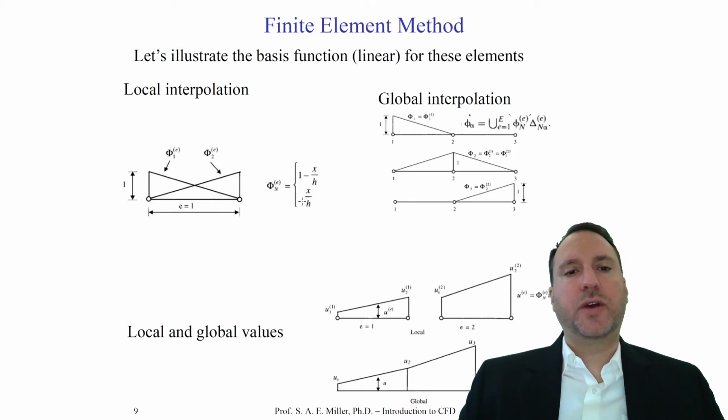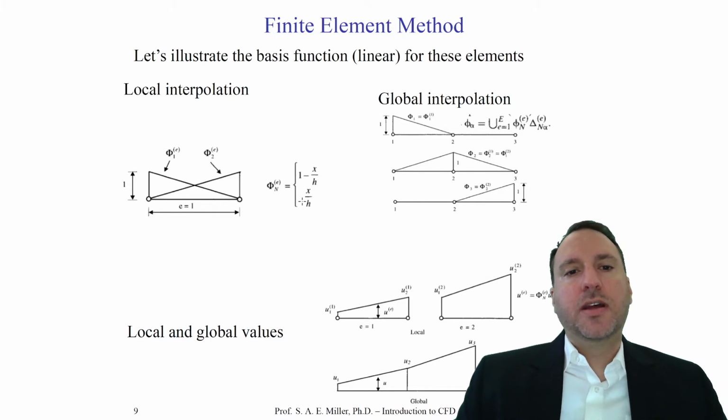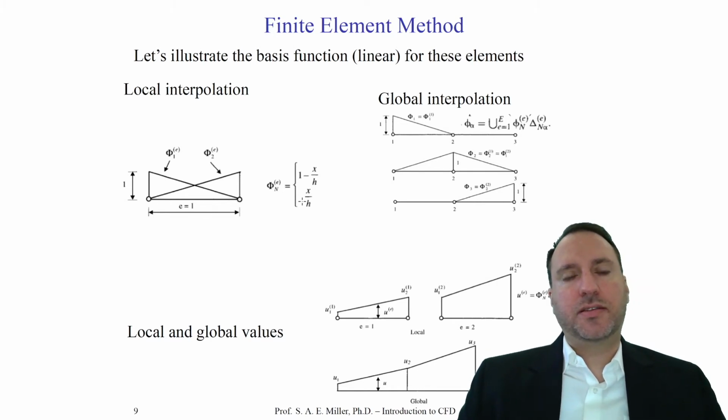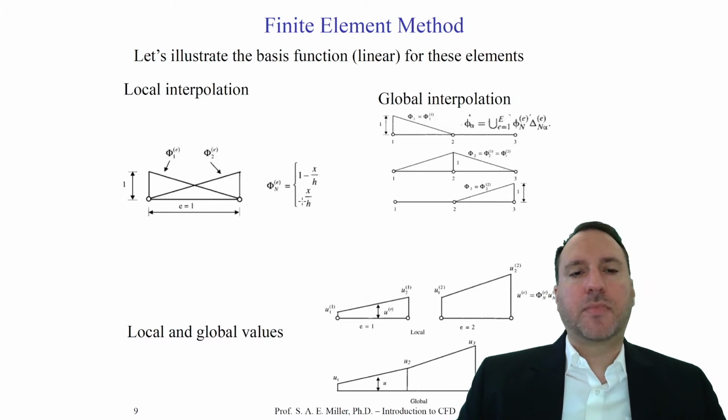These are two linear equations. Now you can stop and think that polynomials of any particular order can also, if they're carefully formulated, have these properties too: that the summation of the elements everywhere in the domain will be unity, especially on the nodes. So the summation of these two basis functions, with their prefactors, will give some kind of solution that's reconstructed of, say, u in this particular problem.